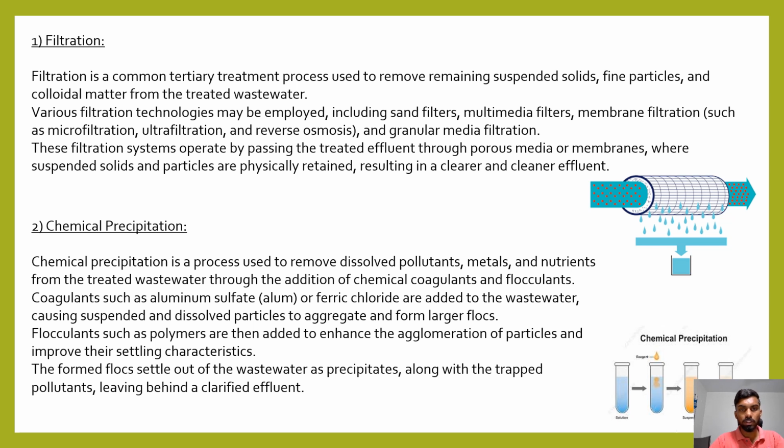Filtration is a common tertiary treatment process used to remove remaining suspended solids, fine particles, and colloidal matter from the treated wastewater. Various filtration technologies may be employed, including sand filters, multimedia filters, membrane filters such as microfiltration, ultrafiltration, and reverse osmosis, and granular media filtration. These filtration systems operate by passing the treated effluent through porous media or membranes where suspended solids and particles are physically retained, resulting in cleaner effluent.